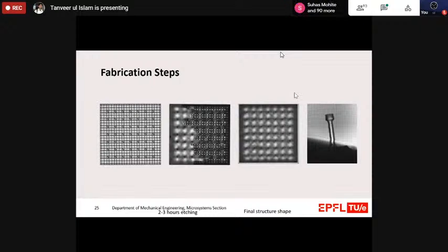So we are still using linear translational stages, which are highly precise, I would say. Because the spot size itself is around 1 micron or slightly more, it may not make sense to have something with resolution less than 1 micron. How about using voice coil actuators then? Yeah, we can. It's just up to us what system we want to use. The basic principle is the same.